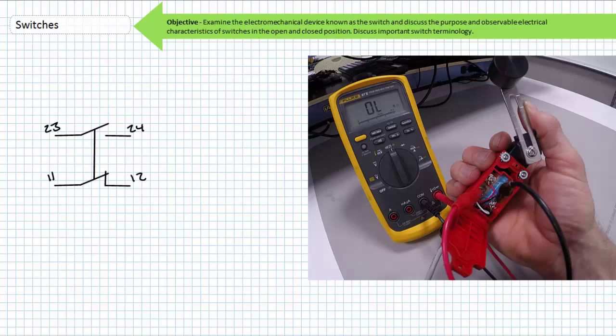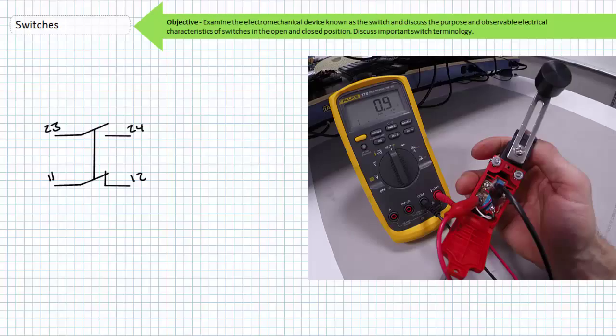It makes sense. A normally closed switch opens up when you actuate it. When the arm is brought back to the center, the ohm meter indicates connection from 1-1 to 1-2. This is a momentary switch because it has returned to its deactivated state of normally closed.